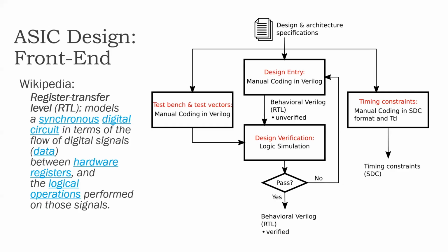The designer is thinking in terms of behavior. And that eases the thought process considerably. And it in fact enables a designer to design very complex and large logic circuits, because they don't have to even think in terms of gates and connectivity. They just think in terms of behavior. So design entry involves behavioral coding, and the language that is commonly used for this coding is Verilog.